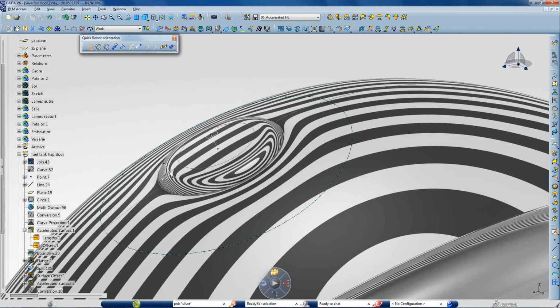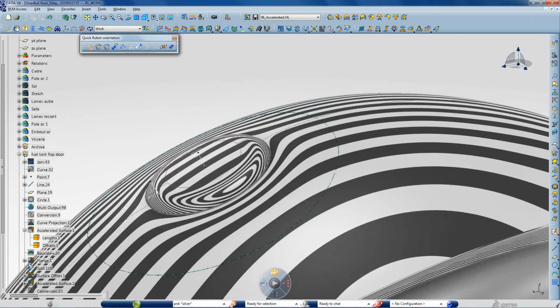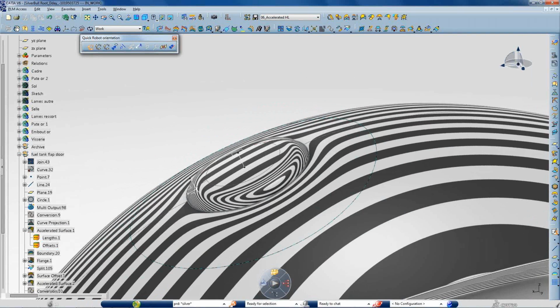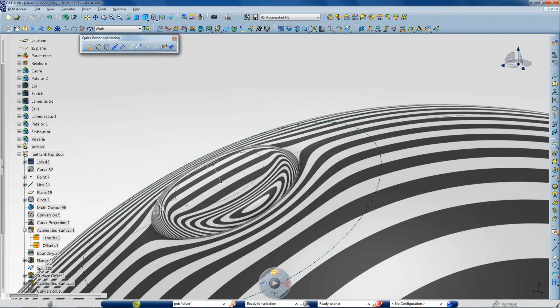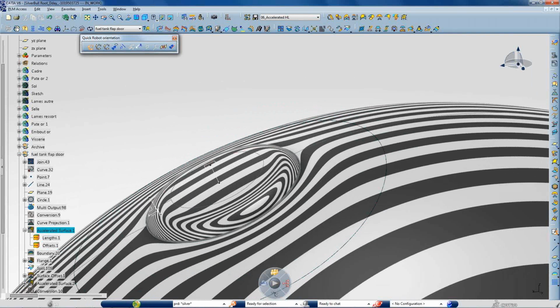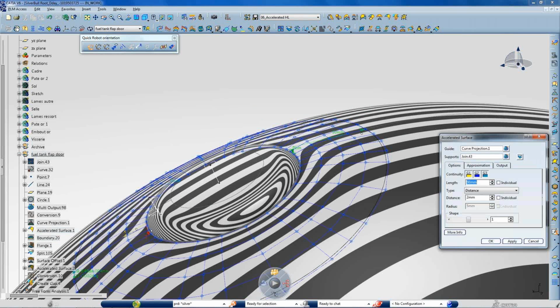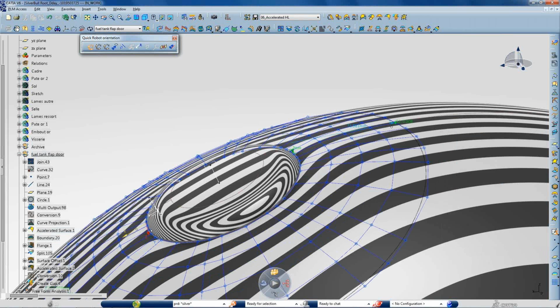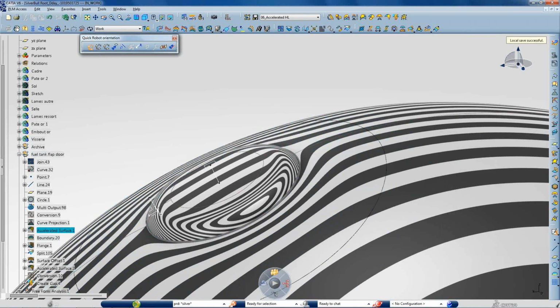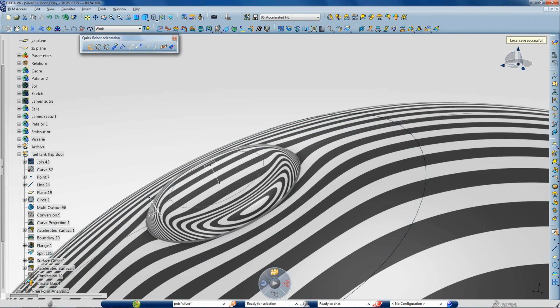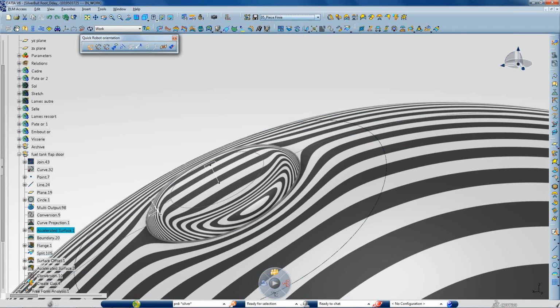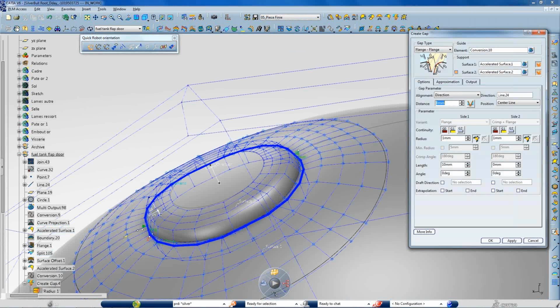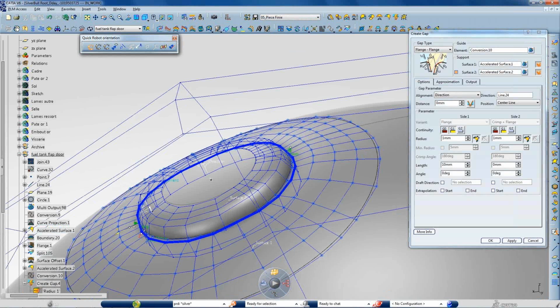So for example, here the designer wants to change it because he doesn't really like how the highlight is going. So you can change this accelerated surface feature from dialog boxes, but also manipulate it directly on your geometry, and you see that it's always automatically updating all the other geometry, like it's automatically doing the stitching of the other surface around it.